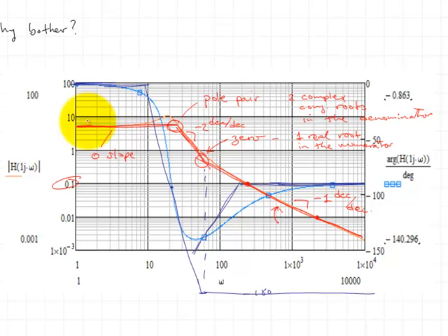And what we're going to do is to look at the transfer function and identify what are the dominant portions of that transfer function within any frequency range. So as we span from very low frequency to high frequency, and we usually do it in decades, we're usually looking over a wide range, many orders of magnitude, what dominates the magnitude of that transfer function, and then we're going to approximate it as a straight line. And then we connect all the straight lines together.